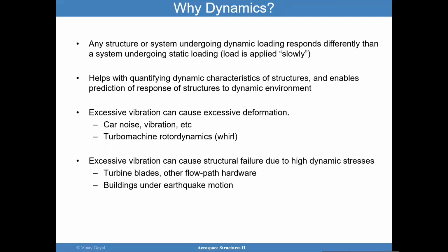Why dynamics? Why do we need to look at dynamics? Any structure or system undergoing dynamic loading will respond differently than a system undergoing static loading. If I apply a load very slowly, there's potential that it will react statically. But if I apply a sudden load to the system, it's more likely to respond dynamically. Now, that's not always the case, and we will talk about that later.